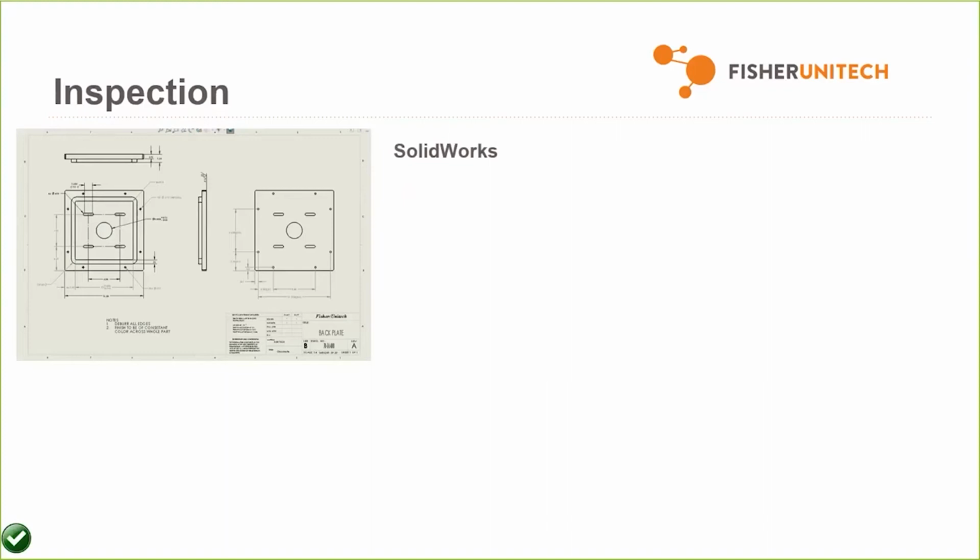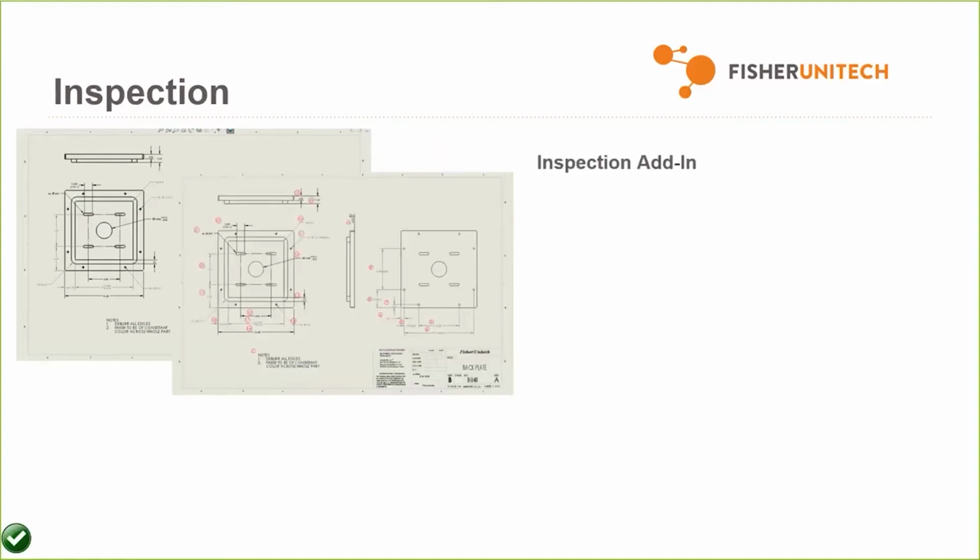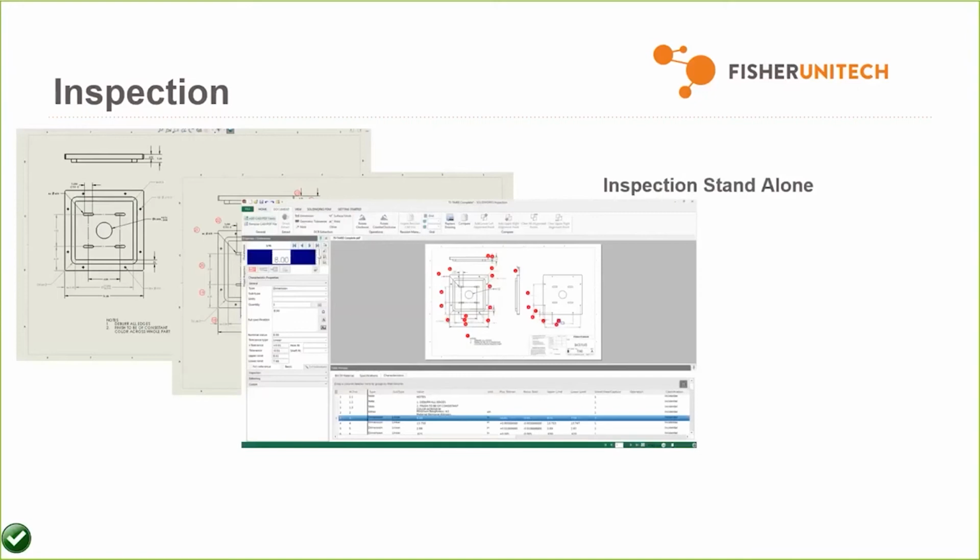In my case, because I am who I am, I'm going to create that using a SOLIDWORKS tool. However you guys choose to generate it is your choice, but just to give you an example here, we'll start with a SOLIDWORKS drawing. I will use the SOLIDWORKS Inspection add-in to create this balloon. All right. I could also use the inspection standalone. There is a standalone interface that goes with inspection because a lot of times the inspectors are not CAD savvy, so they have their own interface here.